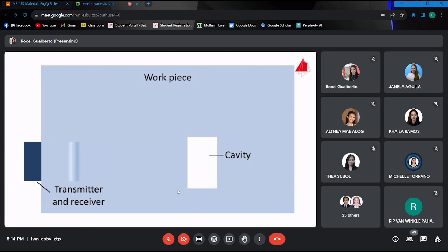For material testing, either the echo of a defect can be utilized, this is the pulse echo mode, or the phenomenon that hardly any sound waves pass through the imperfection. This is called the through transmission mode.